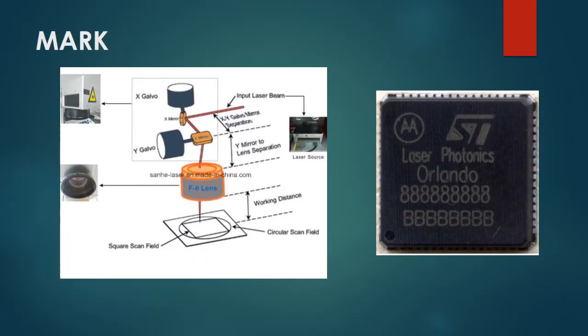Before ending the whole process, marking is required. Marking is the process of putting identification, traceability, and distinguishing marks on the package of an IC. Some examples that are marked on an IC are device name, company logo, date code, and a lot ID. There are two common marking processes, namely ink marking and laser marking.